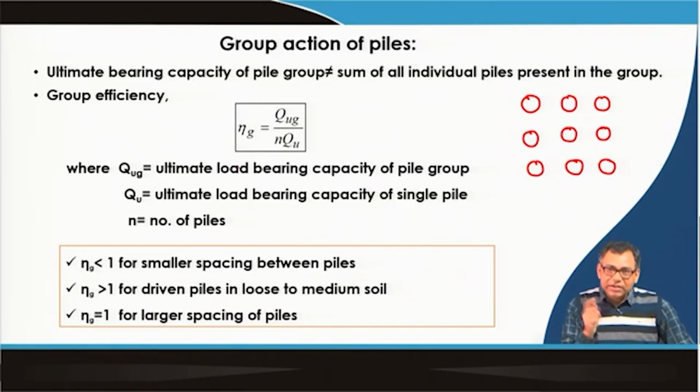In the case of a single pile, that compaction effect will not be that significant. So, the load carrying capacity of the pile, for single pile times the number of piles, will be less than in the group pile or block failure condition, because in that case the total soil within the pile group will be compacted.